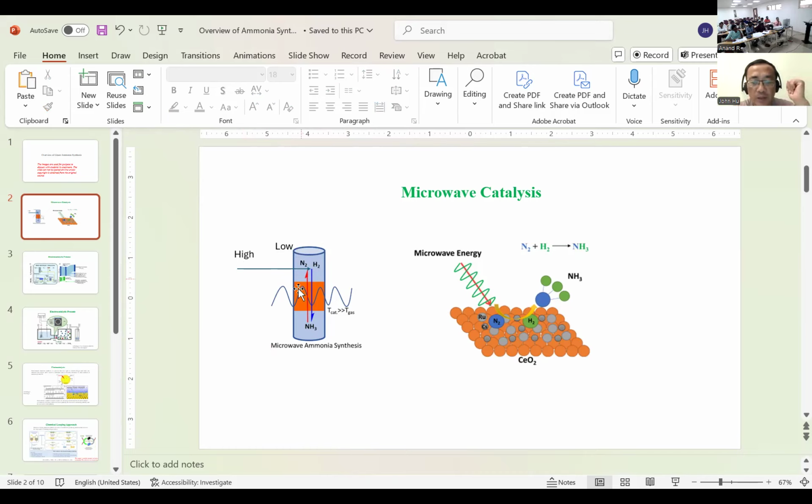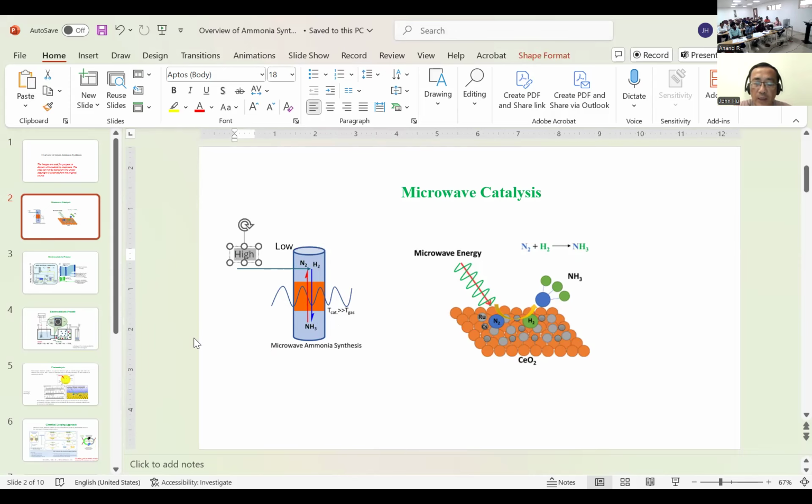So for example, the orange color is the catalyst. If I need this catalyst at, let's say, 500 degrees C, that's the low end. You agree? My heat source has to be more than 500 degrees C, all right? It could be 600 or 700 degrees C. So I have either a fire heater burning very high and then regulate the temperature, or I use conductive heating, but that conductive heating is also high to low. You agree, all right? I want to make sure everyone agrees.